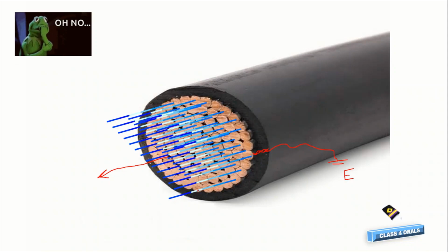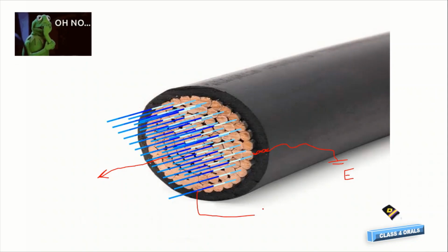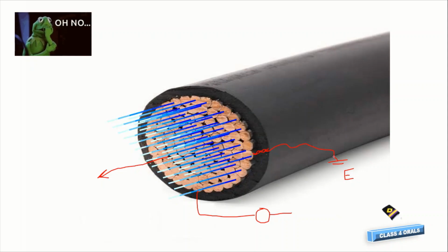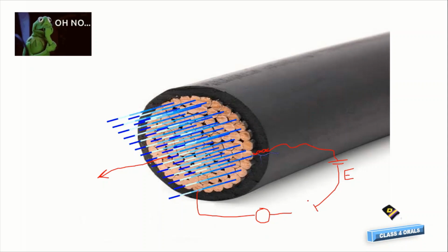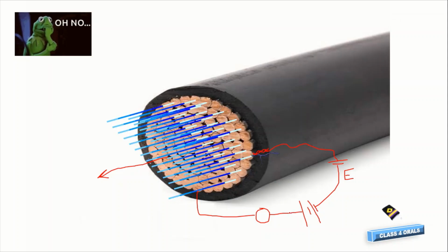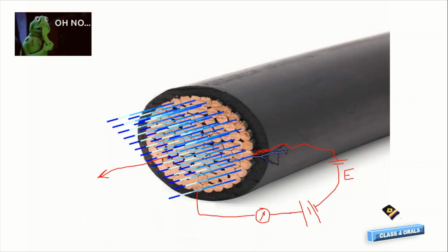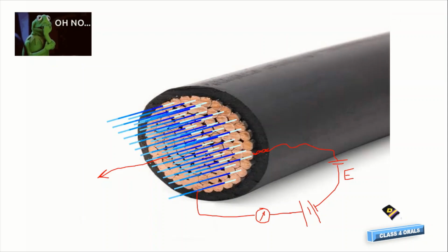And how are we going to test? We are going to put the insulation resistance testing meter between the line which is conducting and the insulation which is earth. We are going to put an insulation testing machine between these two terminals, through which we can find the insulation resistance. So far we have understood the basic concept of insulation resistance.